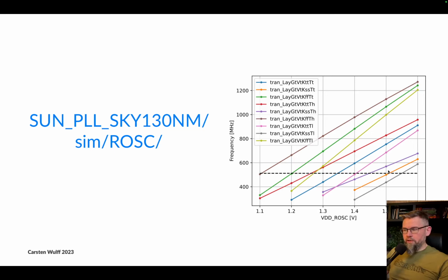And also, when you look at stability, you probably need to look at the KVCO, so the gradient of these lines, in your PLL model, which you might write in Python, across corners to check that it's stable. So you make your oscillator, you check the KVCO, and you use that number in modeling of the PLL. I've put in the link to a PLL that is on my GitHub, and it also includes the transient simulation of the ring oscillator to extract this picture and the KVCO.